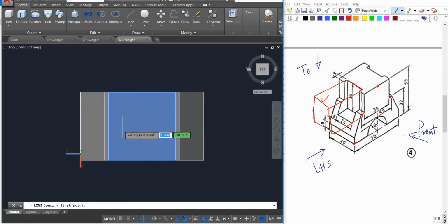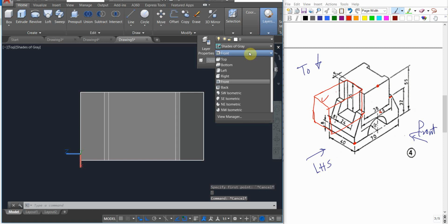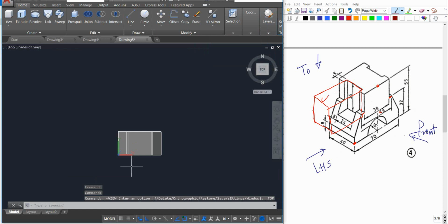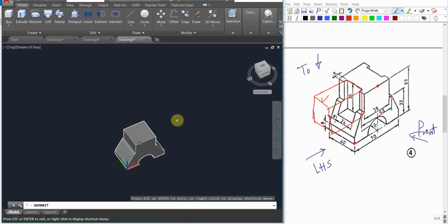I'm just gonna start with a line, and I should start from this point. I'm just gonna move 8 inside, then 5 going back from that point. But by the way, you have to switch the direction. The use plane should be the front, the top view. You have to switch to the top view, so you're gonna see the 2-dimension sketch. The XY plane is already located on the top.